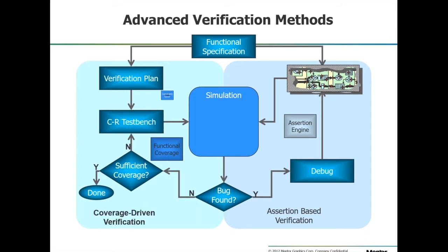The last thing was the idea of a constrained random test bench. Instead of a directed test where I've got to go through every feature and say, I'm going to generate this data and I expect to see this result, the constrained random test bench says, I'm sending these packets of data with a CRC, but my real specification at the system level is that those packets need to be reliably received in an environment with a 10 to the minus 5th bit error corruption.